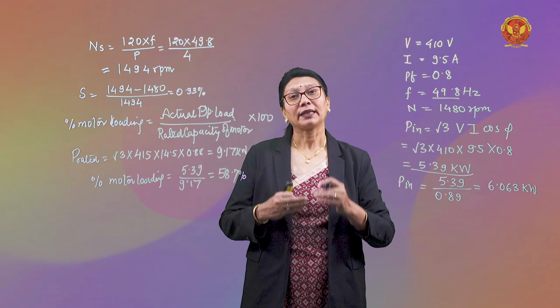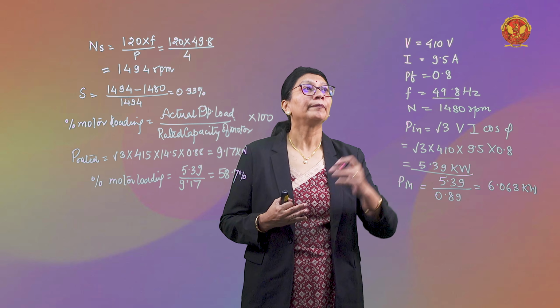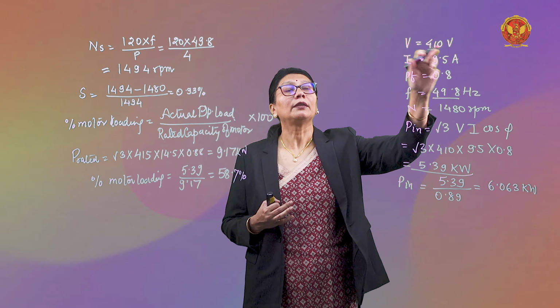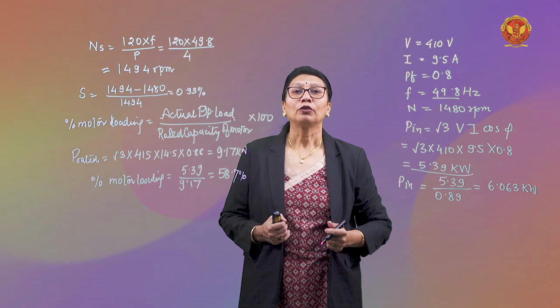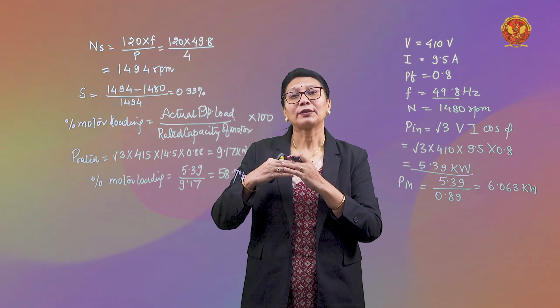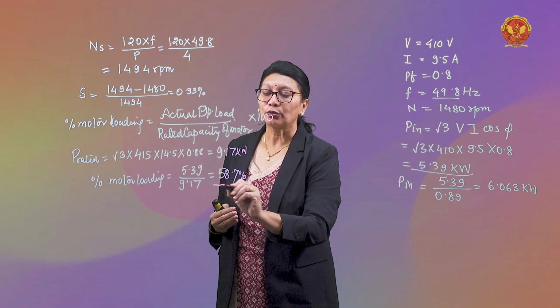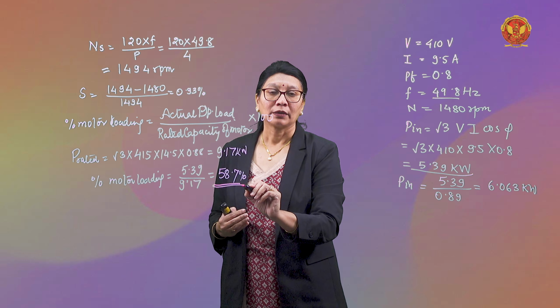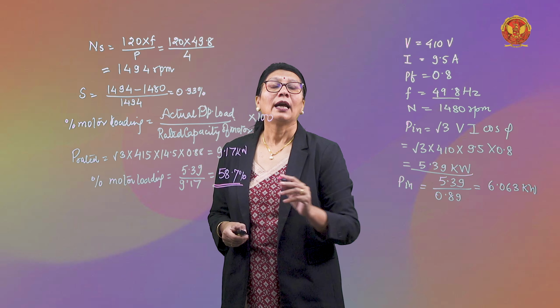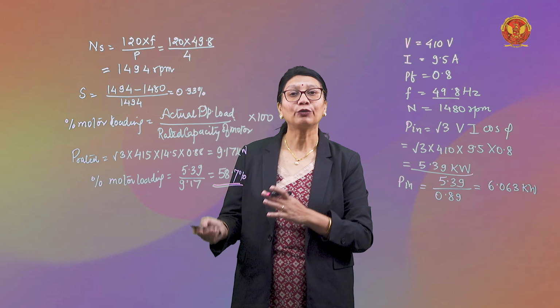जो ऑपरेशन हो रहा है दैट इज एट 0.8 पावर फैक्टर with 9.5 एम्पियर एंड 410 वोल्ट सप्लाई. सो रिड्यूस्ड, आपने मशीन का कॉस्टिंग तो पूरा पे किया बट यू आर लोडिंग इट ओनली टू दिस मच परसेंटेज. So this is derating and we are paying high for reduced services.